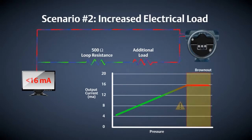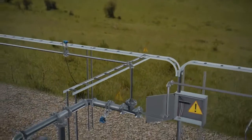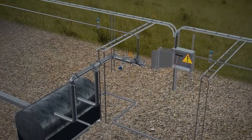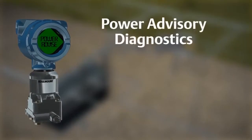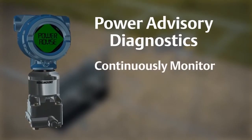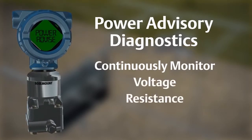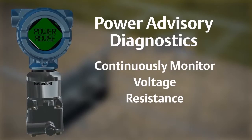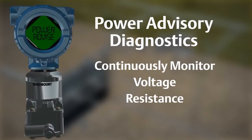What if your transmitter could detect all of these changes that could impact the integrity of your 4 to 20 milliamp loop? Rosemount pressure transmitters with power advisory diagnostics continuously monitor the electrical characteristics of the loop, including changes to the voltage and resistance, allowing you to be alerted to these conditions before they can cause an on-scale failure that may put your process, plant, and people at risk.